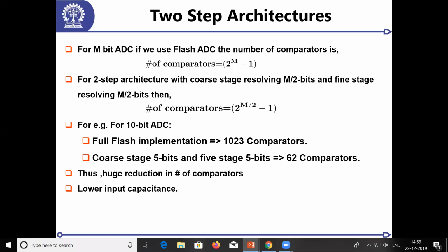And what is the low pass filter in your headphone? It is your headphone membrane. It acts as a low pass filter. It filters and gives you a pretty good accurate signal. Now if I look at this, you sample at a much higher rate here and a lower rate there. So you are trading off accuracy versus speed. So this is a delta sigma ADC.